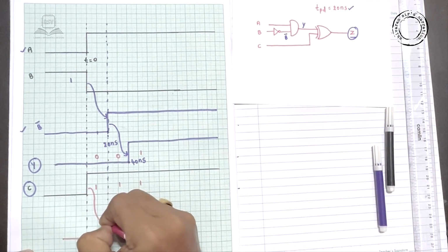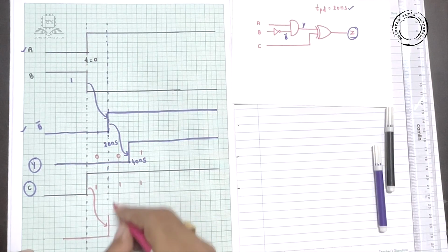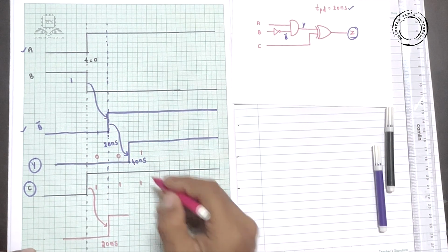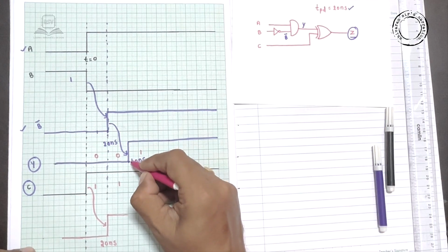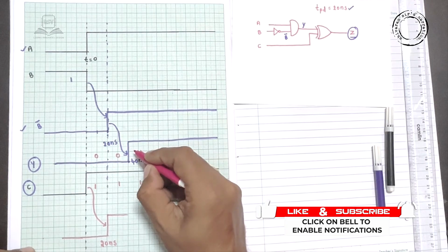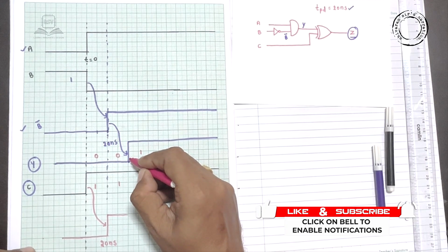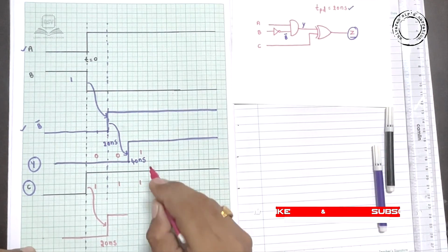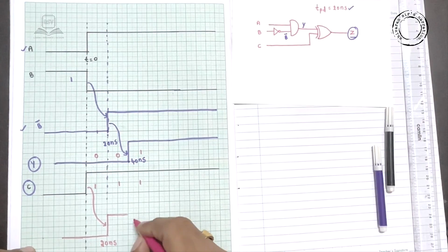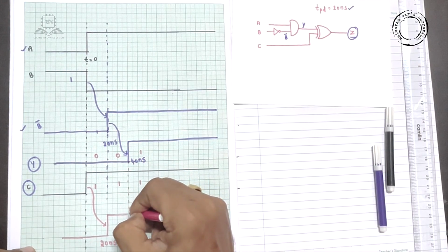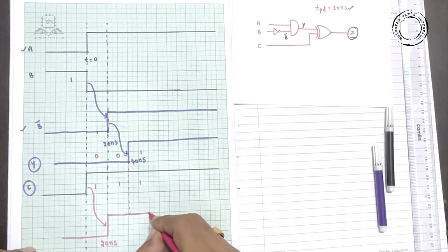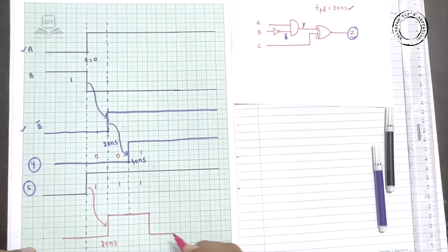That happens after 20 nanoseconds, and yes, again it is 0 1, it's carried forward, but here again the output Y has changed from 0 to 1. Because of this change, the output changes again, because it's 1 1, we will get 0, but you get 0 after 20 nanoseconds. Hence here exactly from here, 20. So after 20, the output changes from 1 to 0.